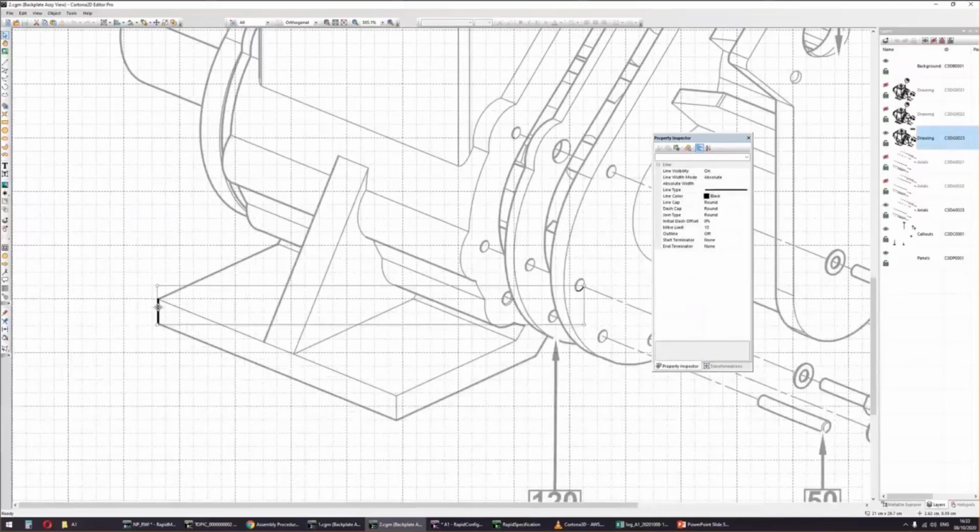Now we right click on the line and find here the new command, find ellipse. Now you can see immediately that it recognized the surface, not the surface, rather the plane that we can make use of. Now the second mode that we can use here is the intersection of two planes, but this is not what we need here. Now we can also specify the diameter right away like this, and that's it.